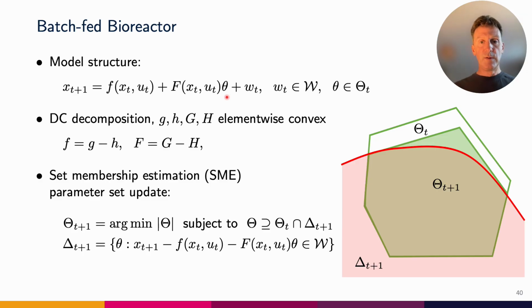So we first reformulate the parameters so that they appear linearly in the system dynamics. Then we obtain DC decompositions for the part of the model which doesn't depend on the parameters, and then another DC decomposition of the part which does depend on the parameters. This lowercase and uppercase f each has a DC model approximation, which we obtain using a DC neural network representation.